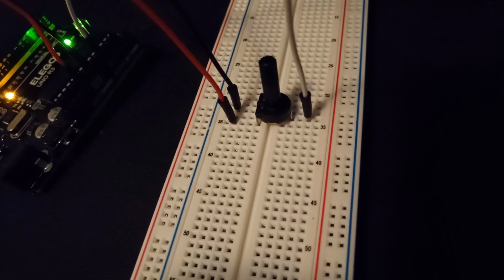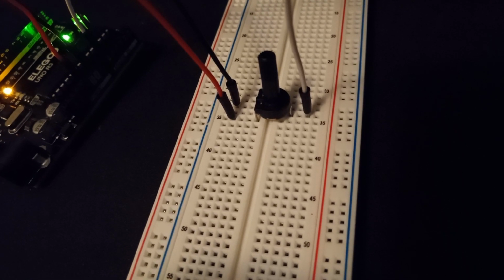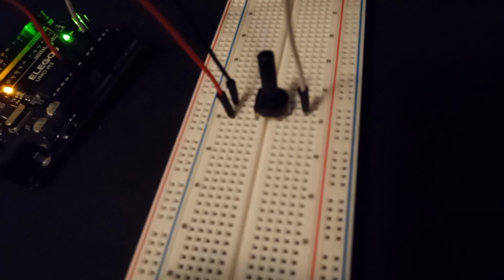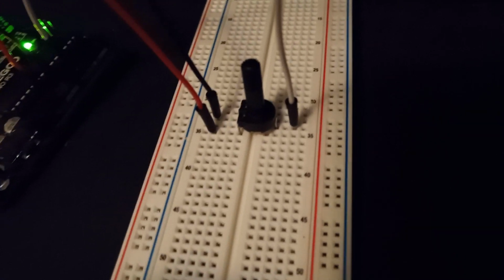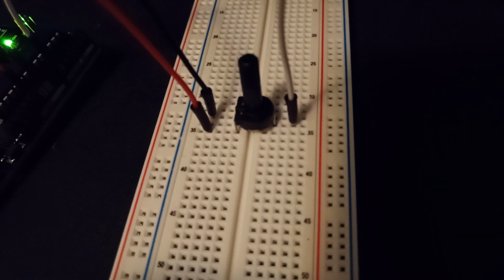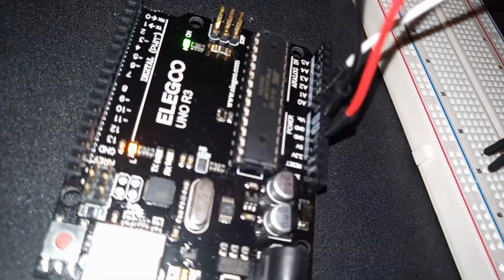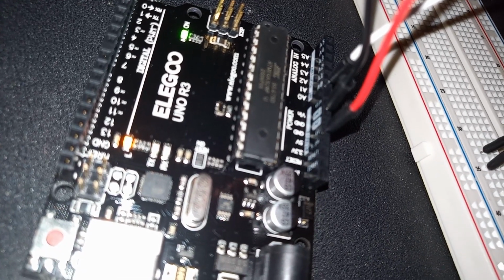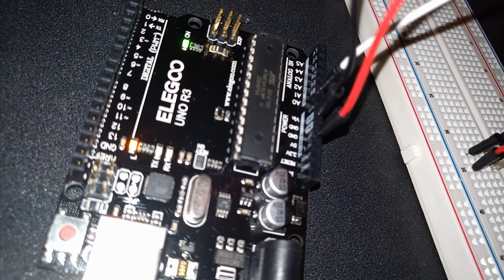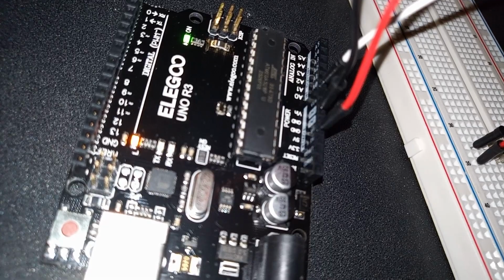This example shows you how to read analog input from the physical world using a potentiometer. A potentiometer is a simple mechanical device that provides a varying amount of resistance when its shaft is turned. By passing voltage through a potentiometer and into an analog input on your board, it is possible to measure the amount of resistance produced by a potentiometer as an analog value.